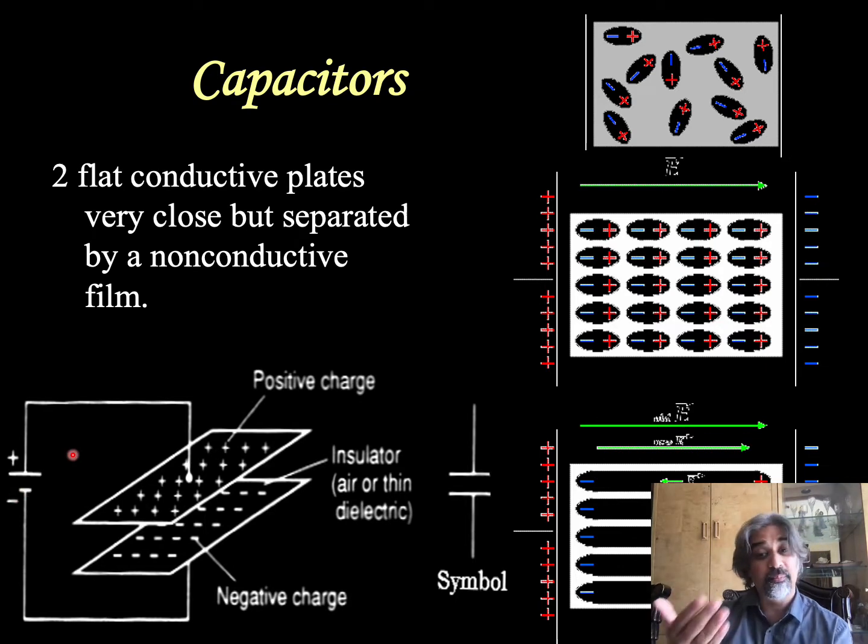So what has happened? Basically, a current has conducted across the capacitor, even though nothing has gone across. This continues until finally all these positives are repelling each other so much that the force of the repulsion equals the force of the push from the battery over here.